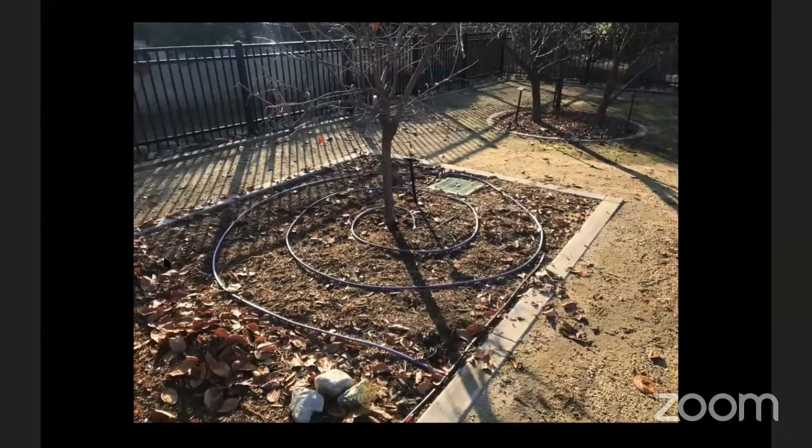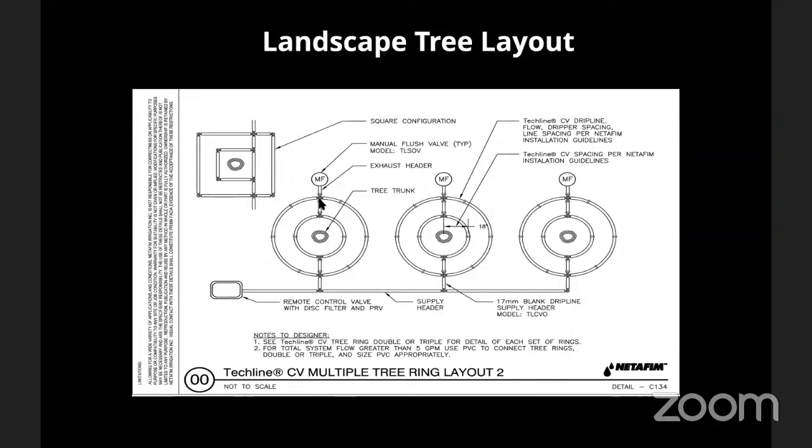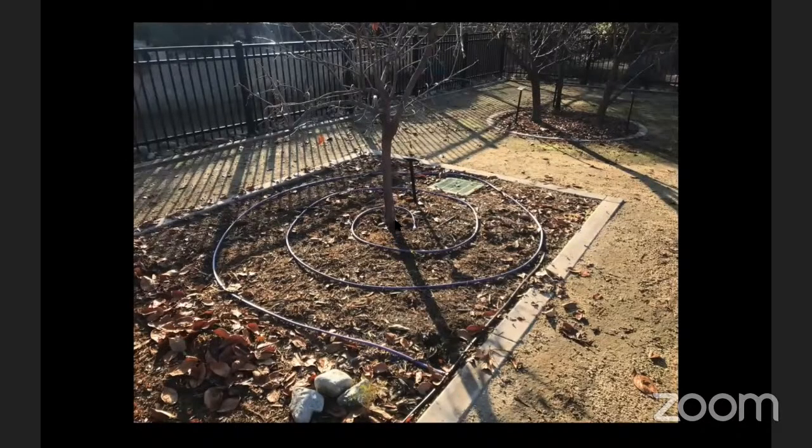If we're not having plants all the way underneath in between the trees, you might have your header. If you only have a couple of things this small, again, based on the linear feet, you might choose to just have the 1/2-inch line, or this could be coming off of PVC pipe if you're doing a bunch of trees. And then what I like to do is, instead of these concentric circles and a bunch of different fittings that you have to push together, I just do a spiral. And that also makes it really easy if you need to change it over time.